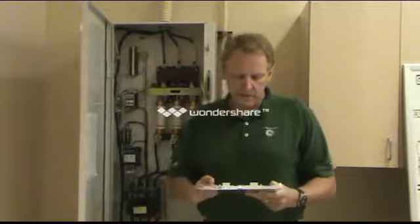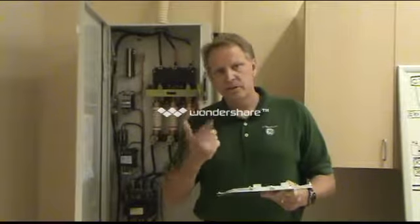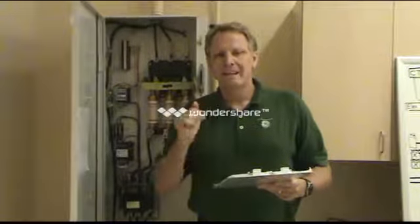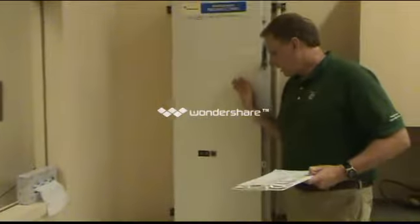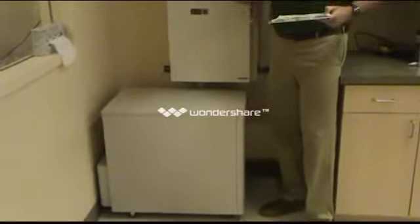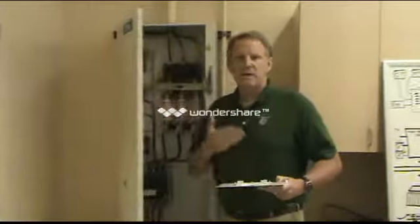All right, the last section on page 2 is the environmental. If you have any issues with temperature, humidity, configuration, egress, whatever it is, this is your opportunity to put it down. At this site, there's an issue with stuff in front of the A1 disconnect panel. You should have some room in front of the electrical panels. This site actually has a UPS right underneath it. So this would be your opportunity to write down that it appears not to meet codes for access.